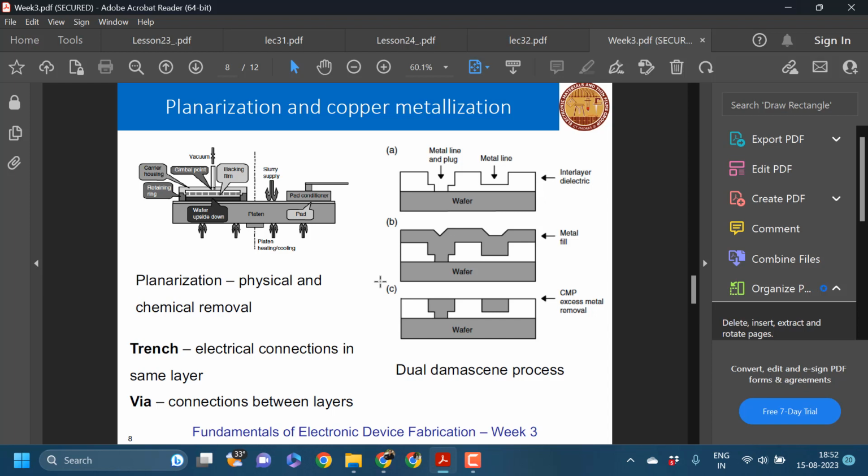Yeah, exactly. So planarization is required because whenever this mask is aligned with the wafer, we require proper alignment and there should not be any residual roughness. And also to get exact focusing of this ICs, we require planarization. So basically, if you Google, you'll be able to get the image of a non-planarized IC with a planarized IC. So in case of a non-planarized IC, aligning the masks or producing the connects will be very difficult and this will induce defects.